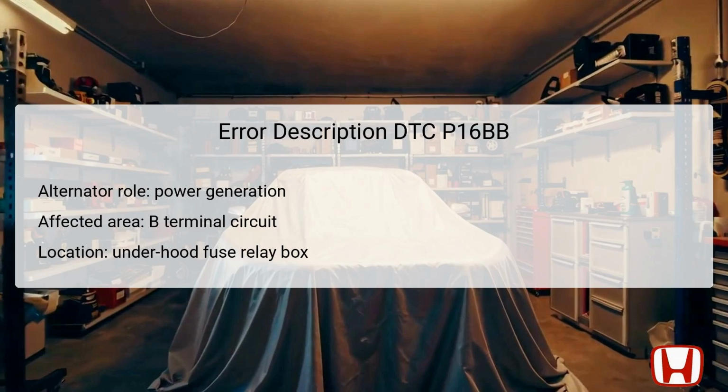When this circuit faces low voltage, it can cause several electrical components to malfunction or fail to operate efficiently. This issue usually necessitates troubleshooting to identify any broken or poorly connected wires, ensuring that the alternator can effectively output sufficient voltage for the vehicle's operational needs.